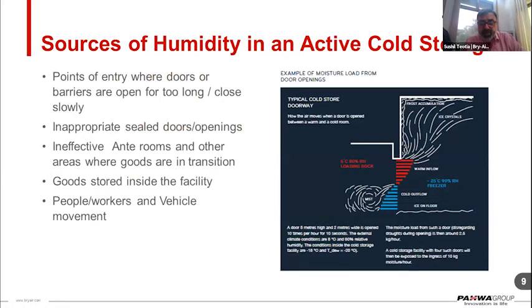And there is another factor which we cannot avoid. There are certain applications where we do not have any anteroom or a secondary room prior to the storage facility. Or maybe the opening time or closure time of the door is very high. That is allowing the moisture to enter again inside the room, and that is disturbing the entire facility maintained by our entire system installed there.